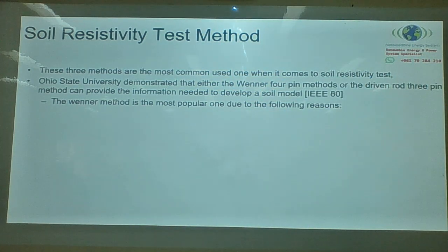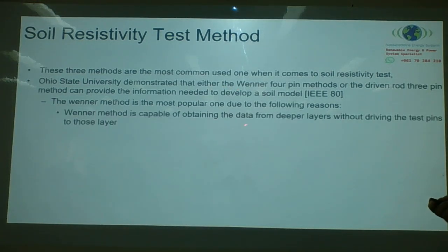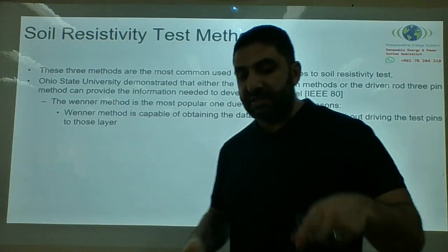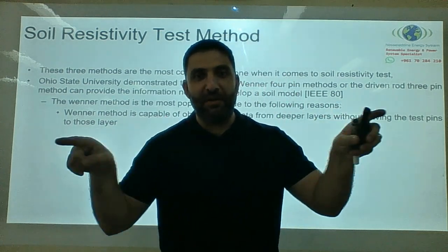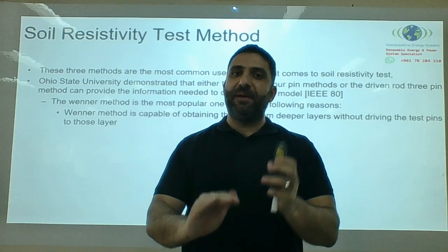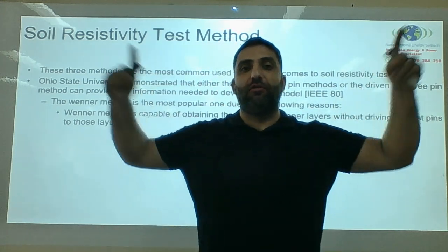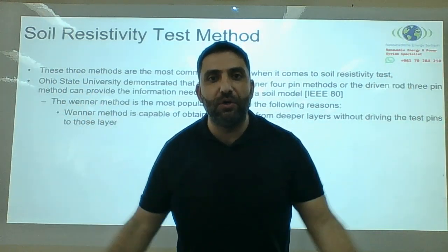soil structure. The Wenner method, as I told you, is the most popular one due to the following reason. The Wenner method is capable of obtaining data from a deeper layer. Remember, the Wenner method goes down to a deeper layer. It doesn't depend on the structure of the soil, but it will keep going deeper. So the further out you go, the deeper it will go.